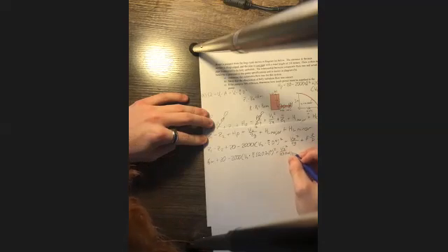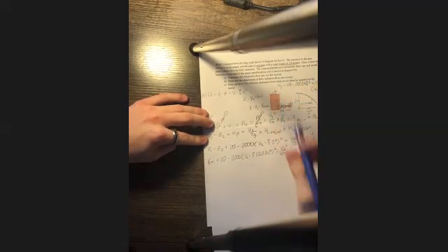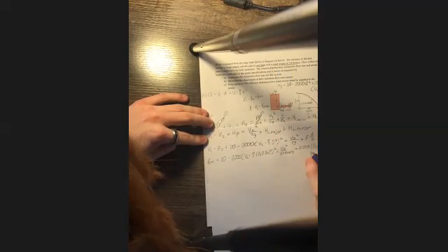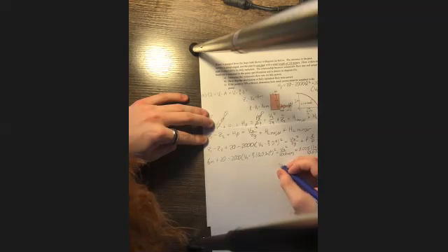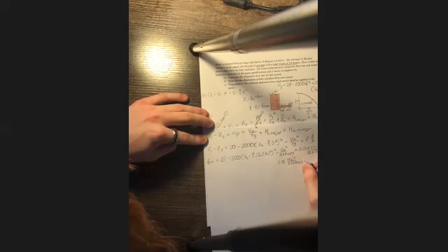The entire thing is squared, equals velocity 2 squared over 2 times 9.81 meters per second squared, plus our friction factor, which is 0.025, times total length, which is shown right here to be 2 meters, over pipe diameter, which is 0.07 meters, times velocity 2 squared over 2 times 9.81 meters per second squared, plus the sum of the loss coefficients, which is 1.5, times velocity 2 squared over 2 times 9.81 meters per second squared.